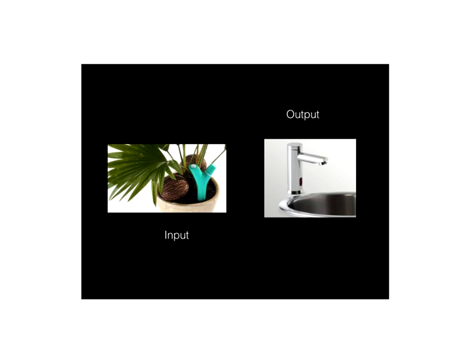Logic can be measured as a voltage. This shows what can be used as a water sensor with an input where it measures if the plant has water or if it doesn't. If the plant has water, then it sends a false signal as a low voltage on a wire, or then back to a controller. And if that controller believes that the plant needs water, it will send a true state to an output, which is, in this case, a water tap that is controlled by a solenoid, which will turn it on and off according to what state it is in the logic on the wire.